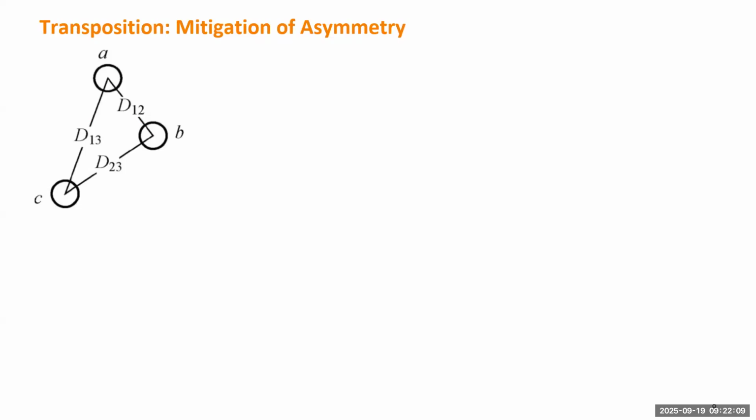So in reality, if you look at the 3-phase transmission lines on the high voltage tower, usually the line is not laid out like a perfect triangle of 60 degrees, right? So usually one distance can be longer and one distance can be smaller. So how do we deal with such an asymmetry? One idea is called transposition.